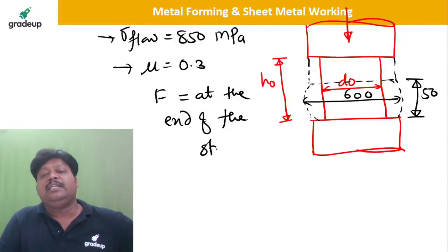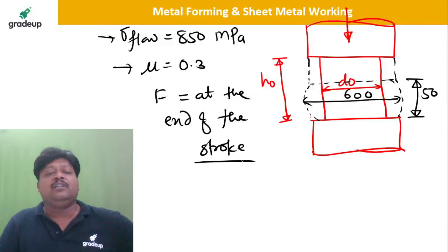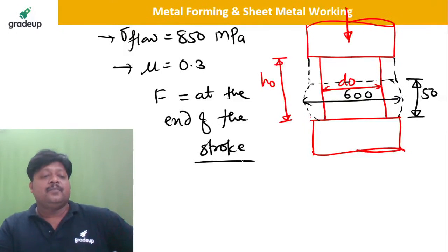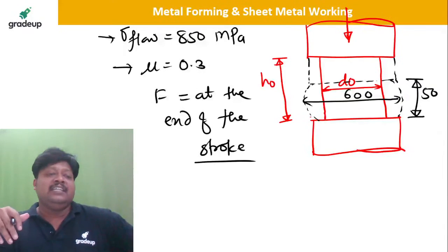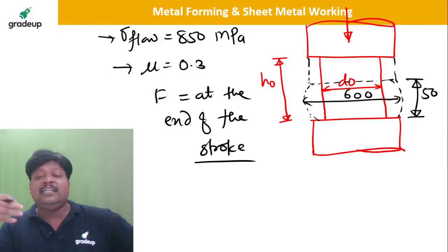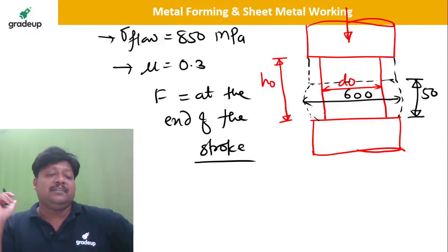Dear students, you know that in the forging operation, this is a very important assumption, that while the diameter increases, that is volume constancy is valid. Okay, you know that if you analyze the forging operation, it will be analyzed that the sticking friction condition and then sliding friction condition, isn't it? Definitely when you are suppressing that height, where it will go for compensation, that is the increase in the diameter.